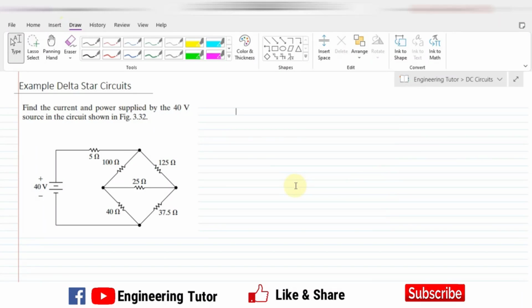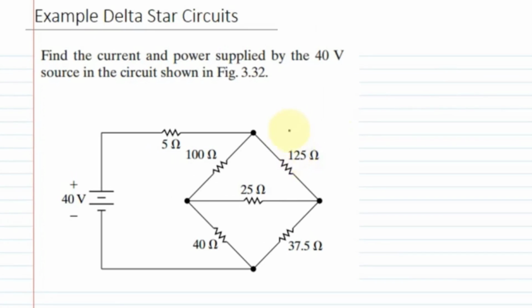So this is our lecture on delta star circuits, that is, how to solve or find the required quantities in a circuit which is neither in series nor in parallel configuration. So this is one of the circuits with such configurations, because here you can see that the 100 ohm and 125 ohm resistors are neither in series nor in parallel, because the two ends are neither connected to each other nor in series with each other.